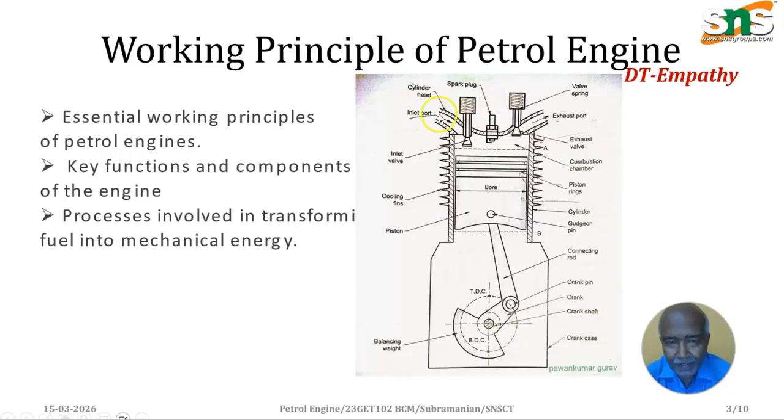When the fuel energy, or the chemical energy, is input into the cylinder, the inlet valve opens and the mixture enters the cylinder when the piston moves from the top dead center to the bottom dead center. This is the bore size. The piston fits equally in the bore, and there must not be any gap, so the piston rings are provided so that there is no gap between the cylinder wall and the piston wall itself.